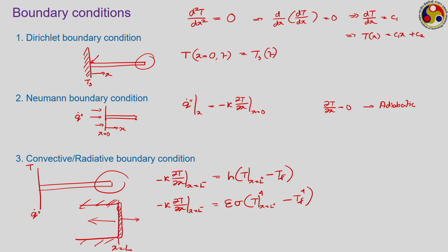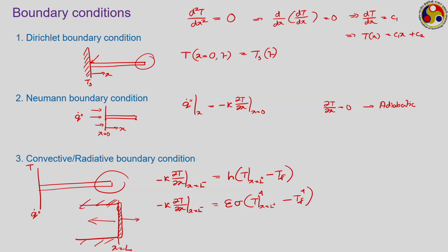These are all very common boundary conditions, and you will encounter numerous heat transfer scenarios in this course itself, where we have to use any one or maybe a combination of 2 or 3 boundary conditions. In fact, for the third one, you may find a situation where both convection and radiation are going on, like the diagram we have seen in the previous lecture, where a surface is receiving energy by radiation, but it is also losing energy by its own emission and convection. If both convective and radiative heat transfers are important, then we have to put all the heat fluxes together.